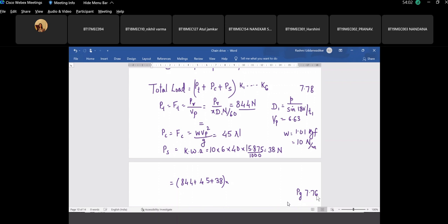The service factor depends upon 6 different factors. First one is the load factor, second is the factor for distance regulation, third is the factor for center distance, next is the factor for position of the sprocket, then the lubrication factor, then the rating factor. So there are so many factors. If nothing is given, then we assume everything as the load factor is constant load, or if you want, you can consider the load with mild shocks or load with heavy shocks.